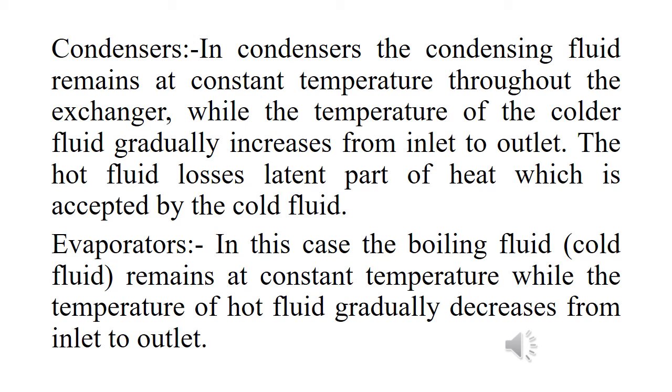The hot fluid loses latent part of the heat which is accepted by the cold fluid, while in case of an evaporator, the boiling fluid, that is the cold fluid, remains at constant temperature while the temperature of the hot fluid gradually decreases from inlet to outlet.